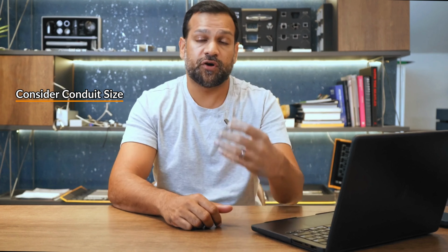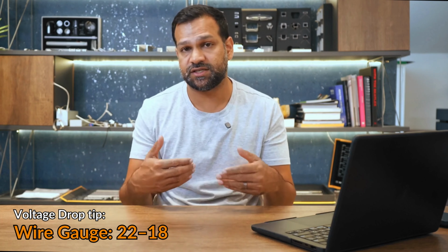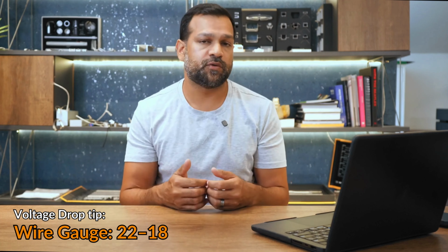So that means you have to consider the thickness of your conduit. You have to consider how far your power supply is, because again, it's low voltage. If the power supply is located really close by, it becomes easy because you can use thinner gauge wires such as 22 gauge, 20 gauge, 18 gauge. But if your power supply and your main controller are really far away, you're going to have to use thicker wires, and you may have to use multiple conduits to power your stair lighting with these motion sensor triggers.